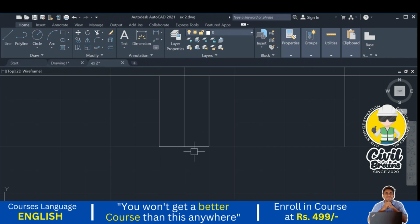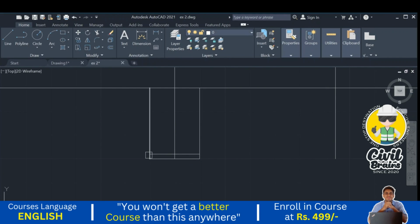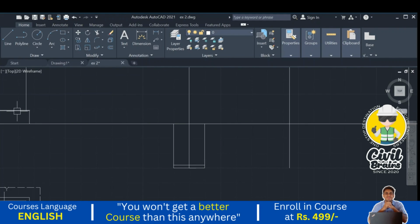Once the excavation is done, next step is we need to provide the PCC. We just go to the offset. What is the PCC thickness? 0.1, it is already mentioned here. After doing the excavation we have provided the PCC. After the PCC we need to provide first step stone masonry, second step stone masonry, then the plinth will continue till this plinth level.